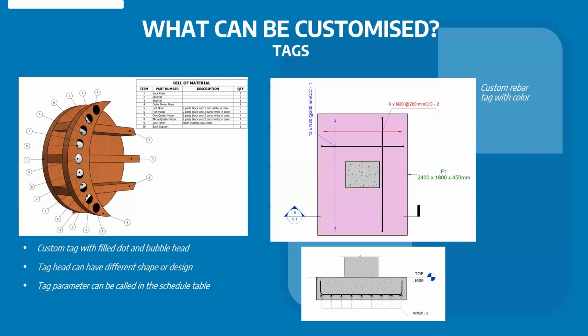You just show one rebar and then call it by the rebar tag, as you see from where to where it is extended, and at the intersection, we put a small dot and drag it as a tag coming here, saying the number of rebars, what kind of rebar it is, plus spacing, and if you have any marking, that's at the end of the rebar, and you have complete control on the customization.